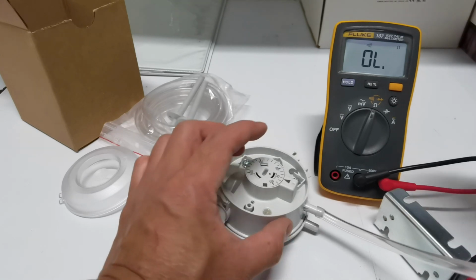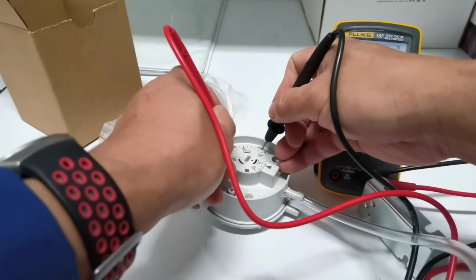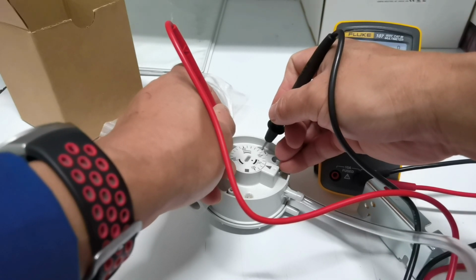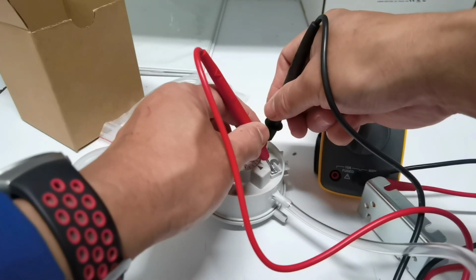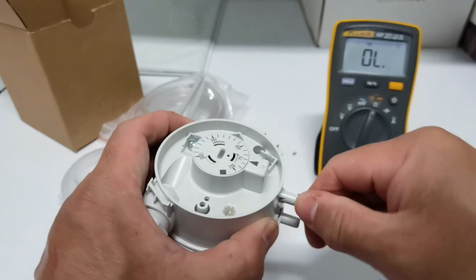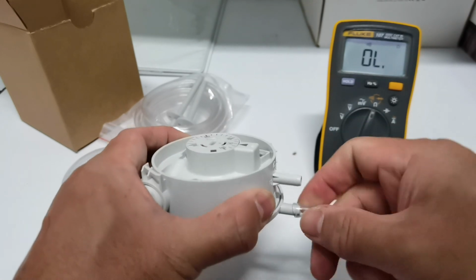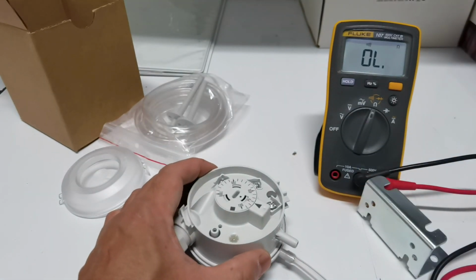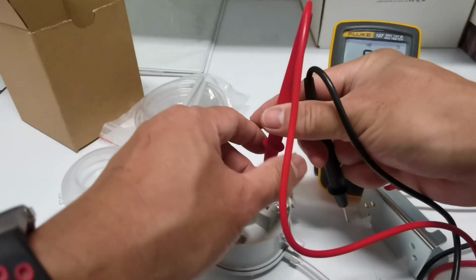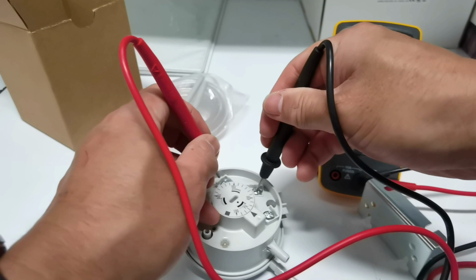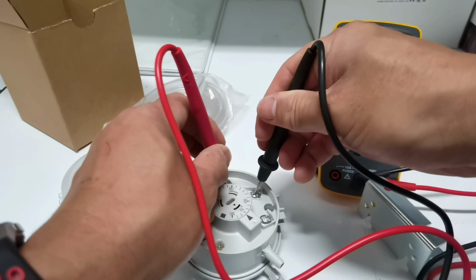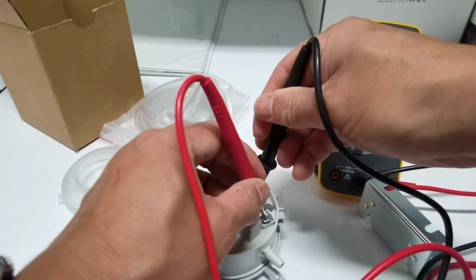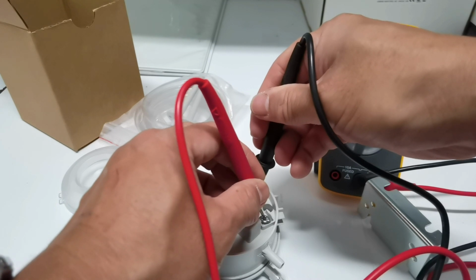As we discussed earlier, terminals 1 and 2 are a normally closed contact. So if we apply negative pressure, contacts 1 and 2 will open, and terminals 1 and 3, the normally open contact, will close. For the positive port, the same thing will happen, but this time positive air pressure should be supplied to the port. As you can hear, a switching sound is coming from the differential pressure switch. It is switching high and low as air pressure is applied to the sensor.